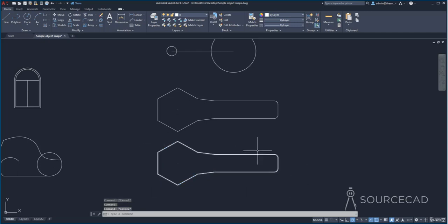All right. Now in this case, you can find out the geometric center or centroid very easily using this snap. So keep it active, move to the line tool, and bring it close to this circumference, and now it will highlight the geometric center, which is also the centroid, as I mentioned. Centroid is simply a point where the entire mass of this object is supposed to be concentrated. So you can make this shape out of cardboard or any metallic sheet, and you can balance it using this centroid.